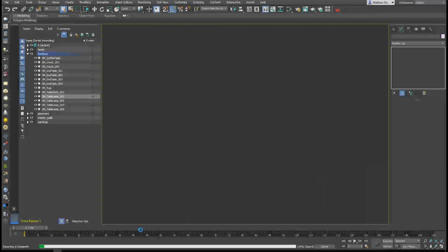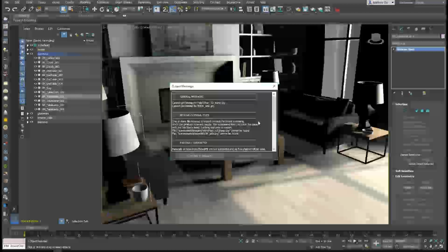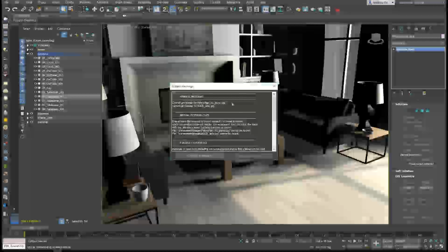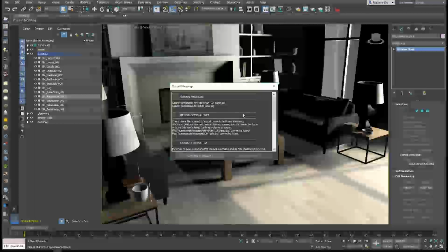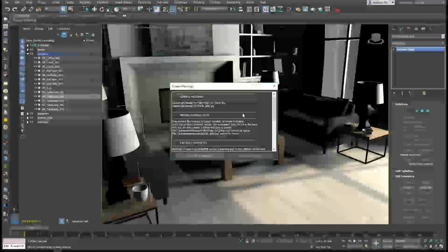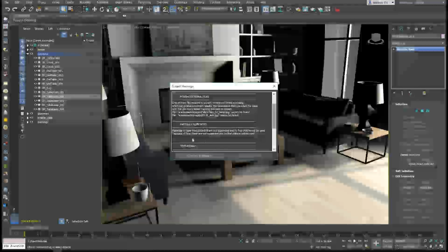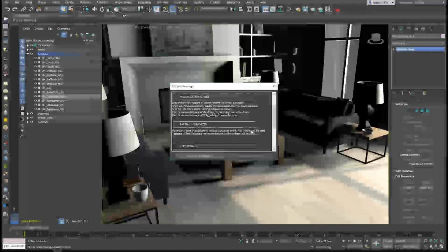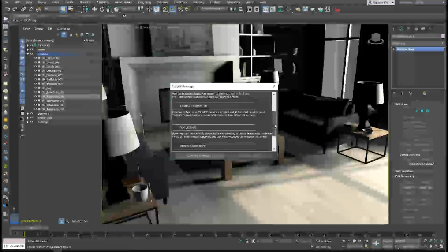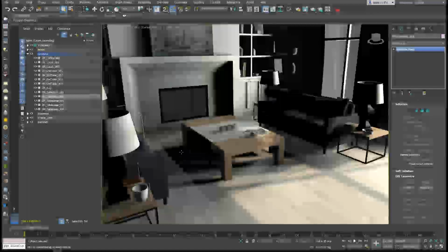So now we can see that Datasmith export is going on down at the bottom here, sending out all of the meshes as part of that Datasmith file. Once the Datasmith export is processed, you're going to get this output warnings window, and it's going to tell you any kind of issues it might have run into while exporting, such as incorrect textures or missing textures. It'll even tell you any kind of issues with partially supported material formats, such as this two-sided V-Ray material here that is not currently supported, missing textures, as I said, and so forth.